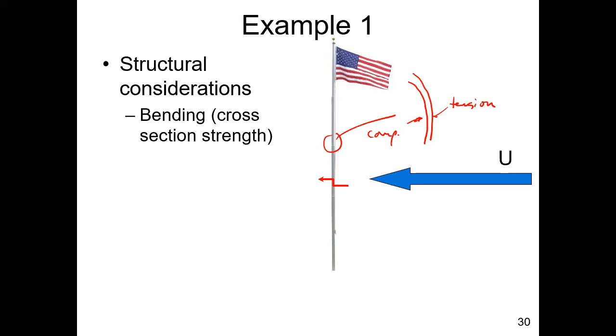So again, that's a material characteristic. And what you would be doing is you would select your material, which then has known stress strain characteristics, and you would size the cross-section anywhere along the system to be able to withstand the stresses you have at that location. So way up here, the stresses are much smaller than the stresses down here. And that's why you'll see in many structures, the structural cross-section increase. It telescopes as you move down the system. So that's one thing you would use this information for.